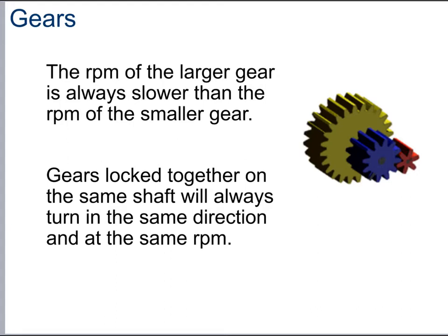Conversely, if a small driver gear is turning a large driven gear, this will slow down the turning speed, which is called gearing down. When it comes to torque, understand that torque is the rotational equivalent of linear force, and speed measures the distance covered in a unit of time. The relation between torque and speed is inversely proportional, so more torque implies less speed and vice versa.